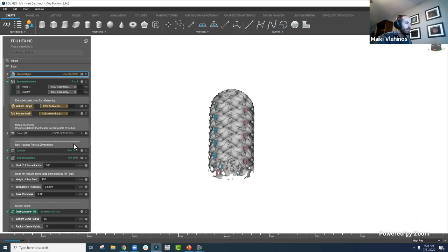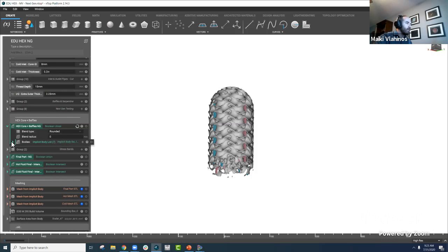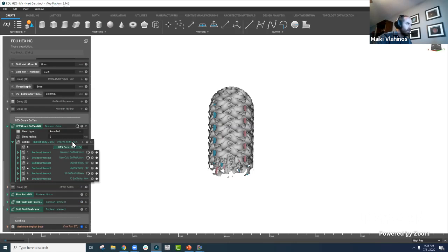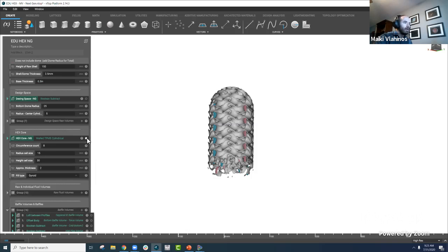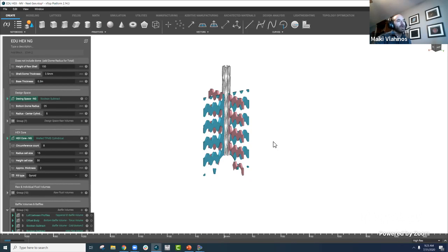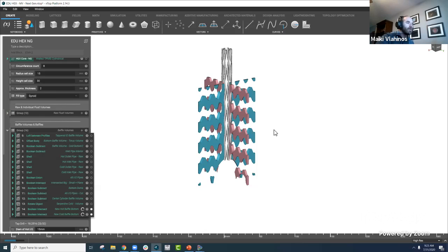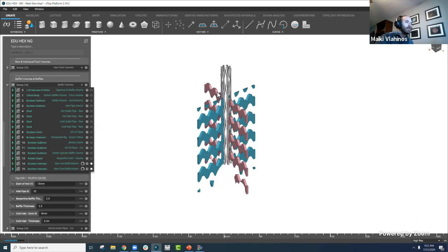But all we do to keep the flow from mixing is, again, just a simple intersect. So we take that fluid domain that we saw, and we intersect it with a body that we want to use to keep them from mixing. In this case, it's just a cylinder in the center or a boxed volume to create those serpentine paths.